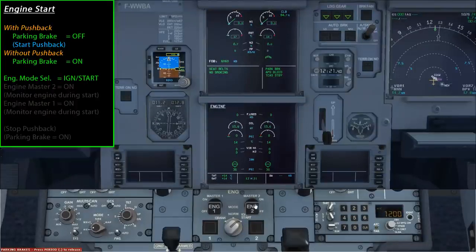So to start the engine, all you simply do, as I said, is just flick the switch. And the engine will now automatically begin to start. So your responsibility as a pilot is just to keep an eye on the engine displays here, just to make sure that nothing abnormal occurs. So you're just keeping an eye there, make sure that the engine speeds begin normally, which you can see there, and you can see that the ignition has started by this indication here.